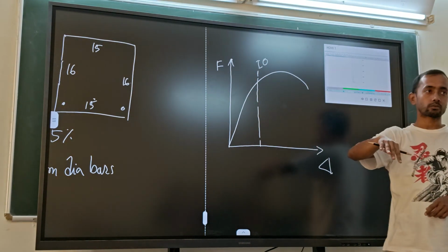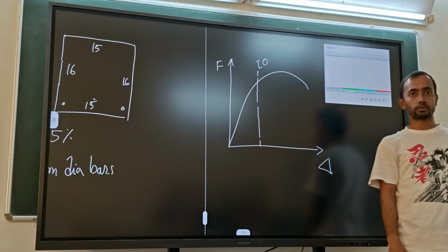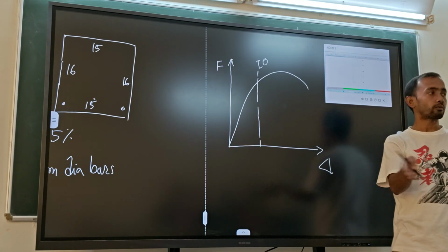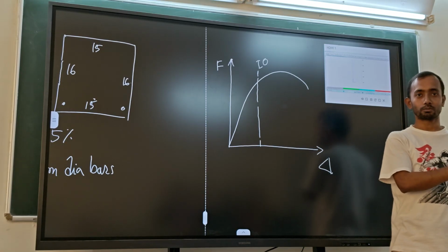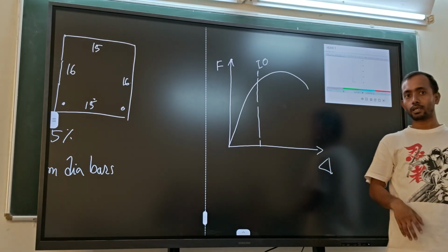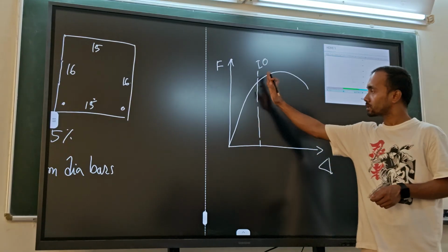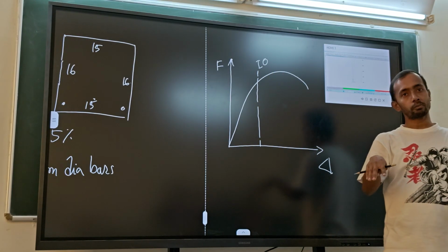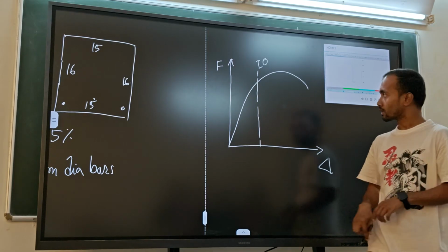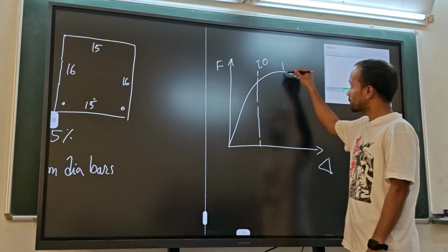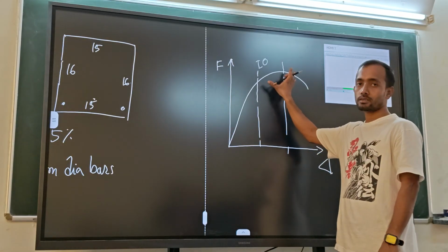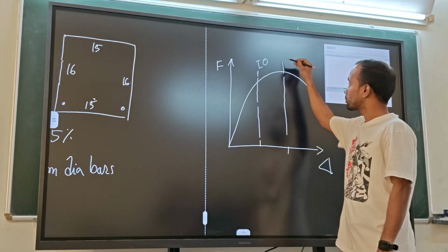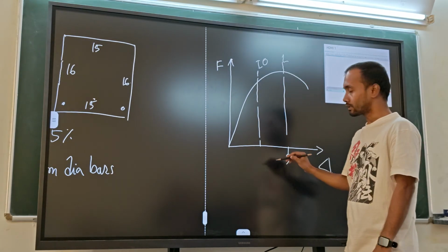That means after an earthquake, for example, suppose an earthquake happens today, as soon as the alarm comes, we have to vacate as much as possible. Now after the earthquake, if the building performance is within this range, we will be allowed to occupy the structure immediately. But suppose the structure is performing in this range, somewhere beyond IO there will be another level called LS.